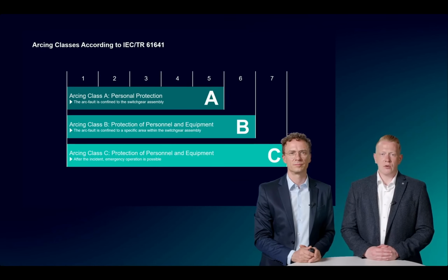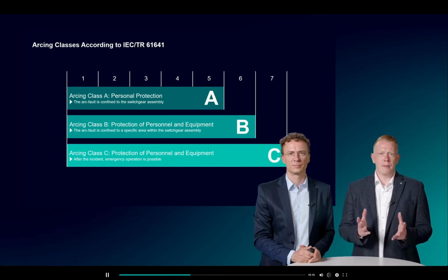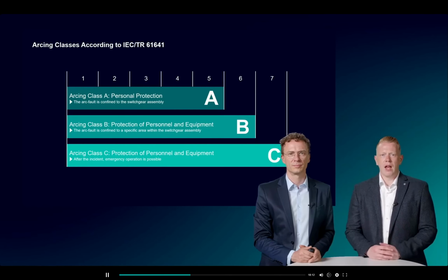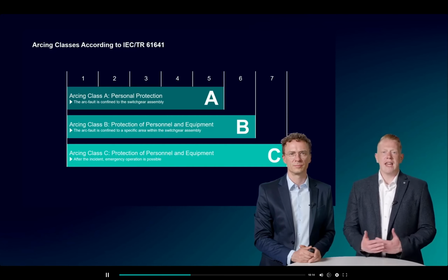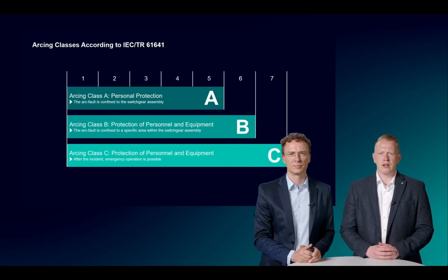That means feeders with a total of 7 transformer stations in between, and 3 transformers which transform down to the distribution level, 20 kV, down to the low voltage level, 0.4 kV. And the important thing is that these feeders are radial. That means on the bottom here, these connections to the area are open.